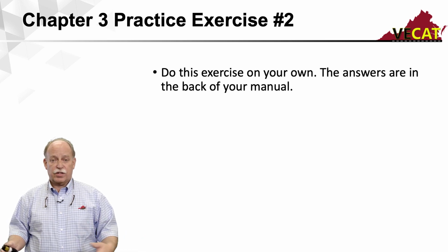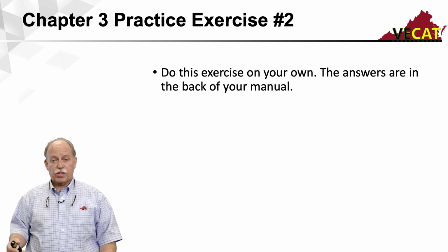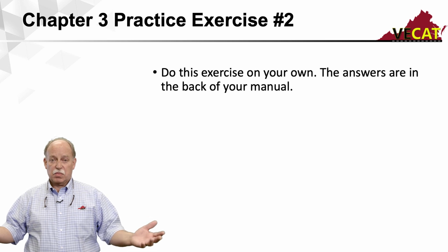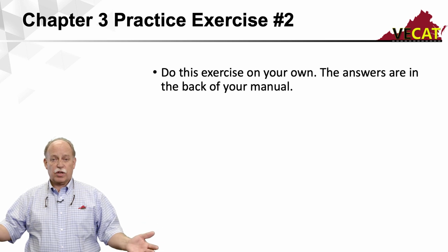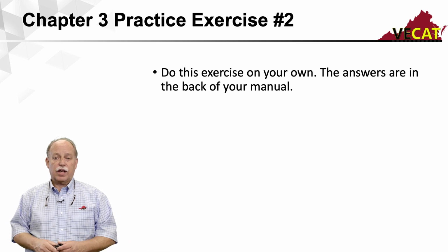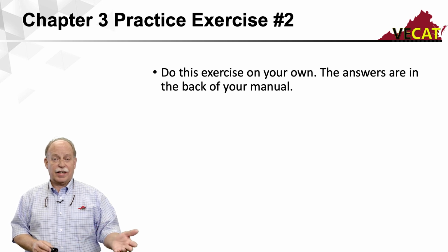You'll see in many instances you might find an answer that's in the standard specifications, but it may also be in the supplemental specifications. In that instance, what rules? Well, the supplemental specifications would overrule the standard specs. So you'll have to go through these questions to get yourself comfortable with ensuring that you're looking for the right answer and that you find it in the right place.